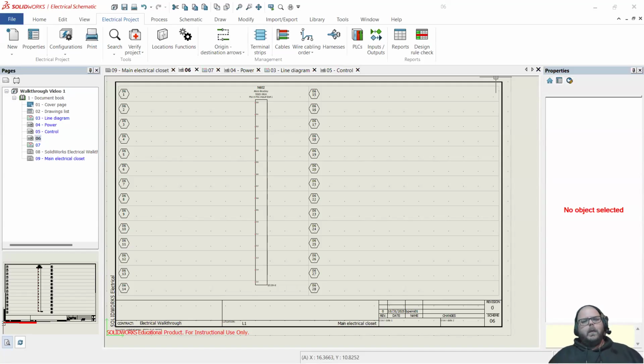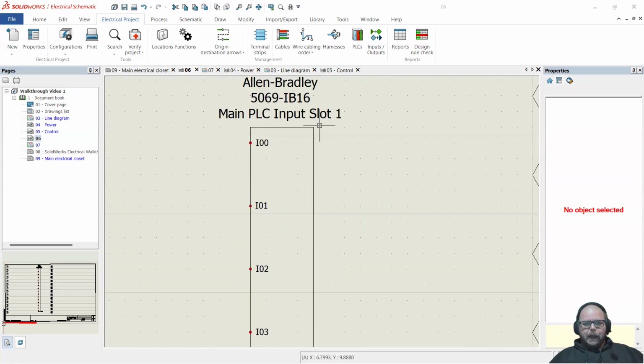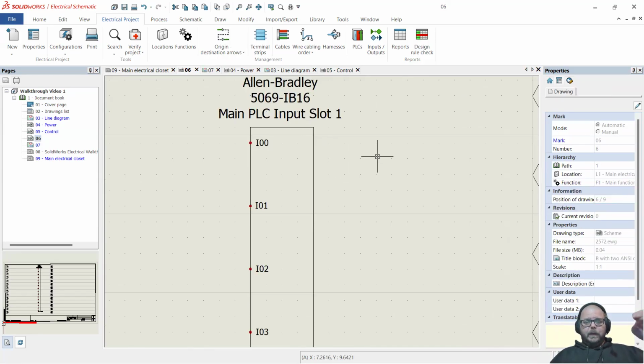In this video, I want to walk through how to create a PLC using SolidWorks' built-in PLC manager. PLCs can be way simpler than what I'm about to show. PLCs can simply be us dropping in symbols, like in a previous video, I demonstrated dropping in and also creating an IO card, right? This is enough. Just dropping in the parts, drop in a PLC, the actual CPU, drop in a power supply, can actually create a PLC.